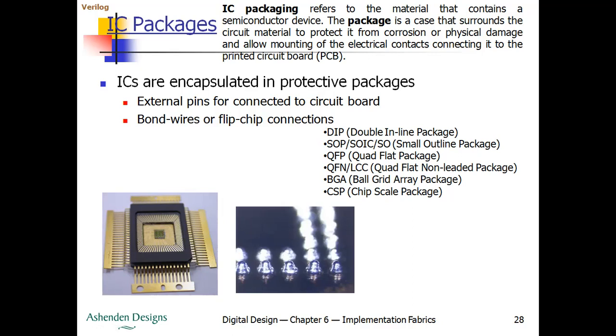For high pin count and good package ICs, the use of bond wires will have mechanical problems and delays, and those mechanical problems and delays will reduce the performance of the signals, and the signal will degrade. Therefore, we use the flip chip technology. Flip chip technology is basically used to avoid the signal degradation due to the mechanical problems and the delays involved in the signal.